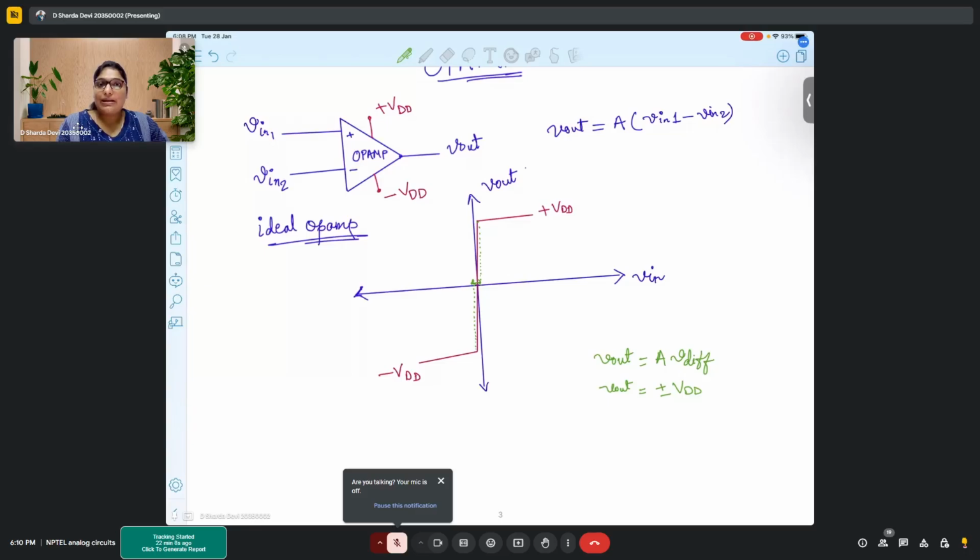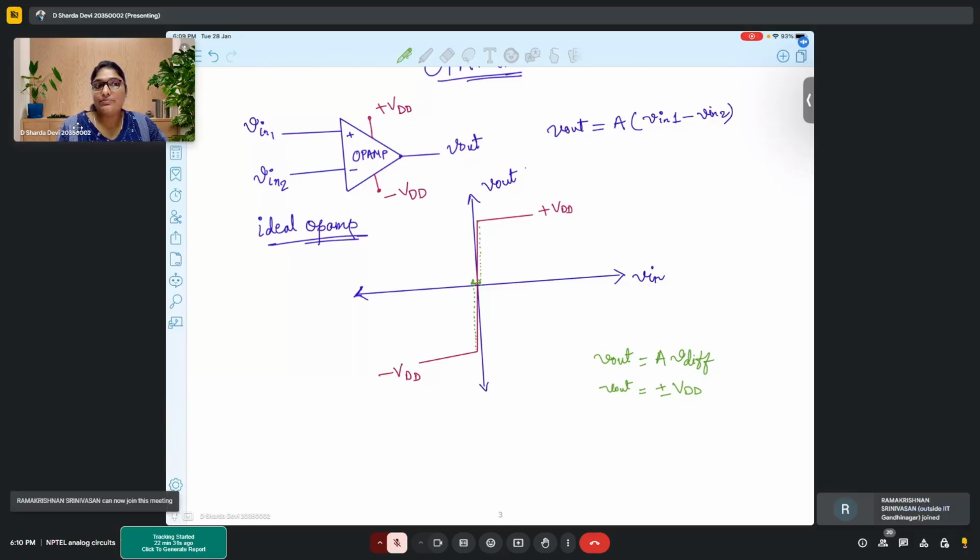But rather than being amplified, if anything else happens to the system or to my signal, we call it that our signal is distorted. And saturation is one of those distortions. The moment you encounter distortions in your output signal, that basically means your information is lost or damaged, which you don't want. So that's why your input signal range should be in this linear range of amplification.